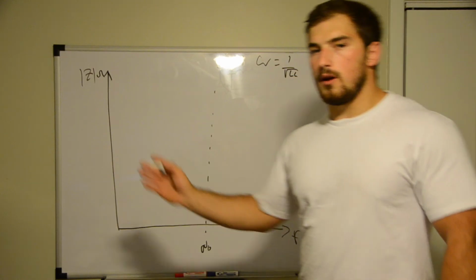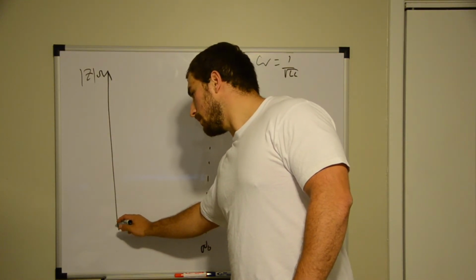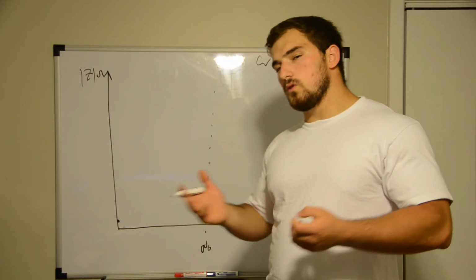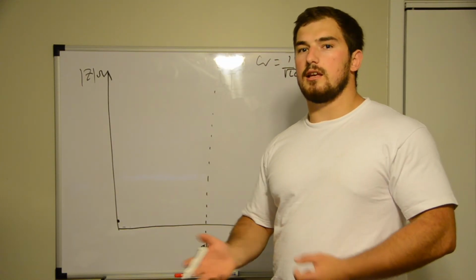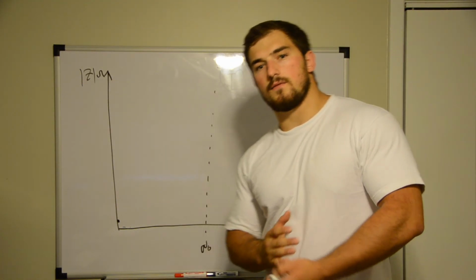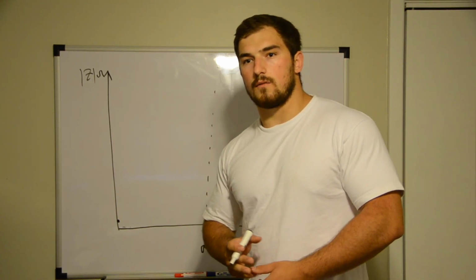So, as we talked about earlier, at these low frequencies around here, the impedance is going to be low because the inductor is usually made out of copper, other stuff, which is highly conductive, so resistance is going to be low. And as the frequency gets a little bit higher, it starts acting like an inductor.